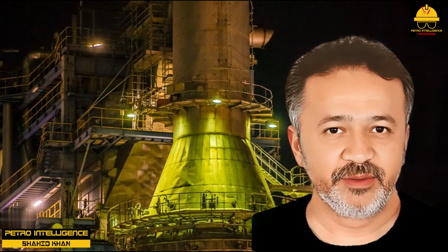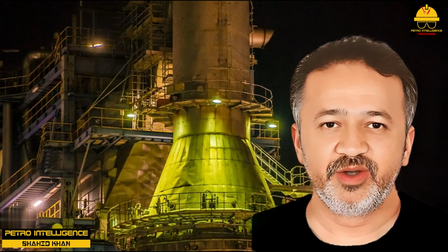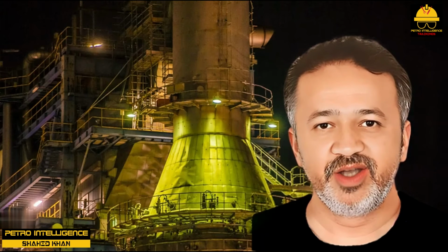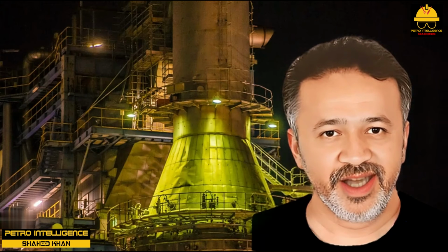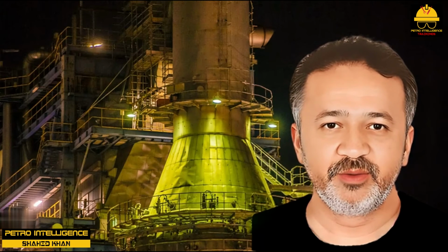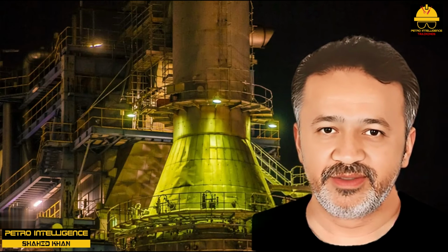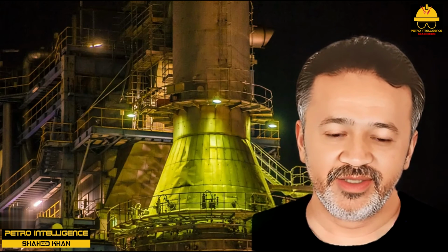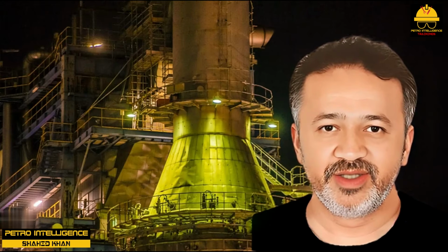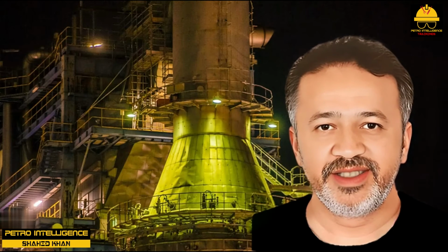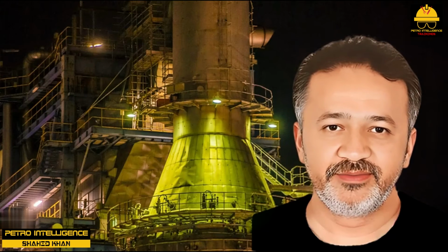I noted that the top of the boiler chimney was about 1/3 of the diameter at the base of the chimney. The reason for this large reduction in chimney diameter is to help induce a draft by increasing the velocity of the flue gas in the upper portions of the chimney. Neglecting frictional losses, the draft induced by increasing velocity due to the reduction in chimney cross-sectional area is as discussed in the video on draw-off nozzle hydraulics, in the section on nozzle exit loss calculation.